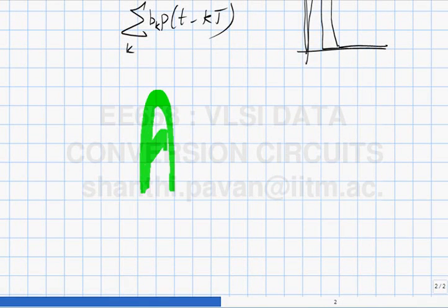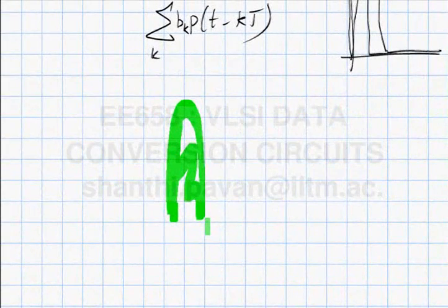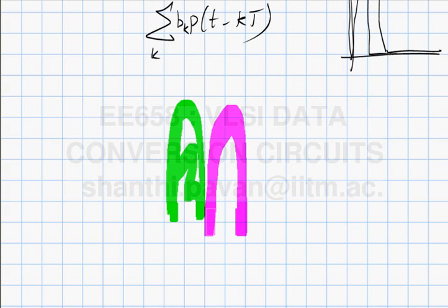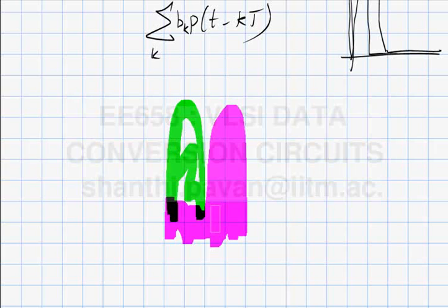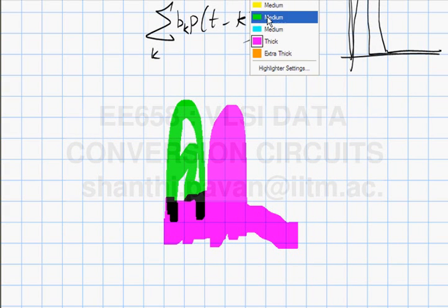If you're supposed to transmit stuff within this band, and to maximize the number of users, your neighbor is basically sitting at, is doing this, okay. This is okay. Now, if he is distorting, if there's a lot of nonlinearity in all his transmission, what will happen is that his spectrum will spill into neighboring channels, which looks like noise to you, because you don't really want to listen to what he's saying, right?